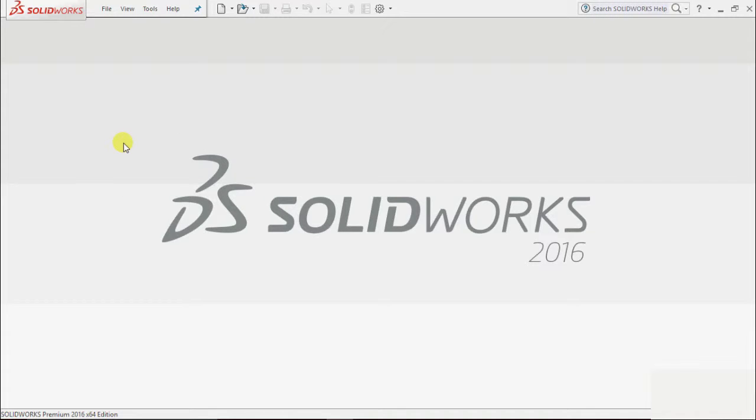Welcome to SolidWorks tutorials. In this tutorial, we will learn how to draw the sketches in SolidWorks 2016. To go to sketch modeling, first we have to go to part modeling. And here's the method to go there. Click on this file tab and click new.